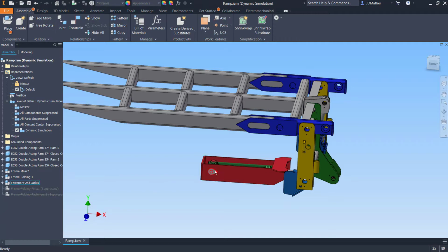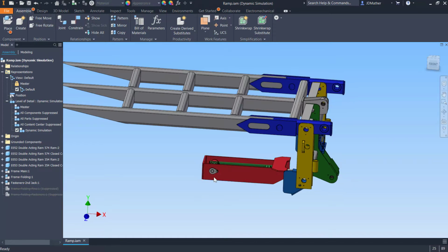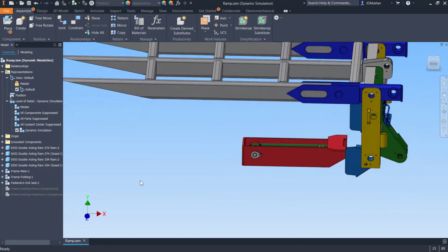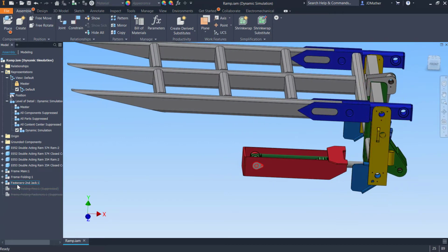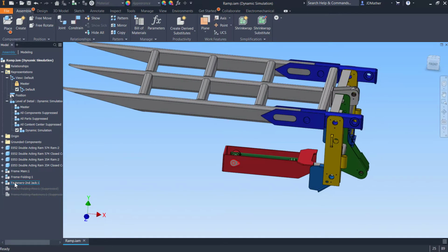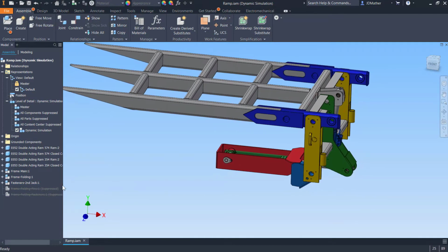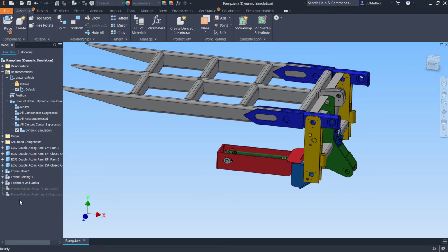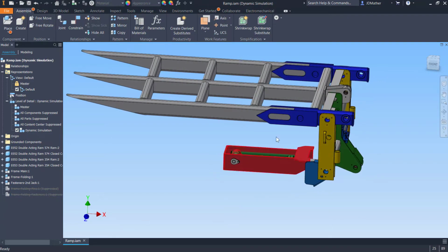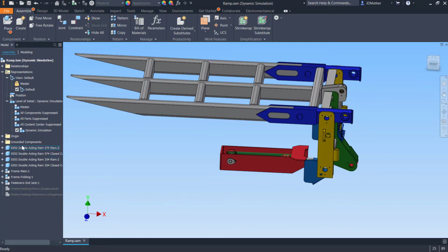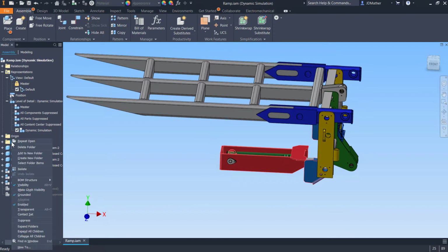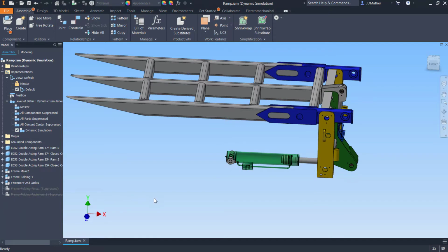Now the fastener here would be added after this hydraulic cylinder is put in here, and so I could leave that as a subassembly, and I'm just trying to decide whether I want to do that as a separate folder or if I want to leave it as a subassembly. I guess I'll leave those as a subassembly. Alright, and then I'm going to turn off the visibility of those components for now to get those out of the way. So I'll right click on the grounded components and turn off the visibility of those.